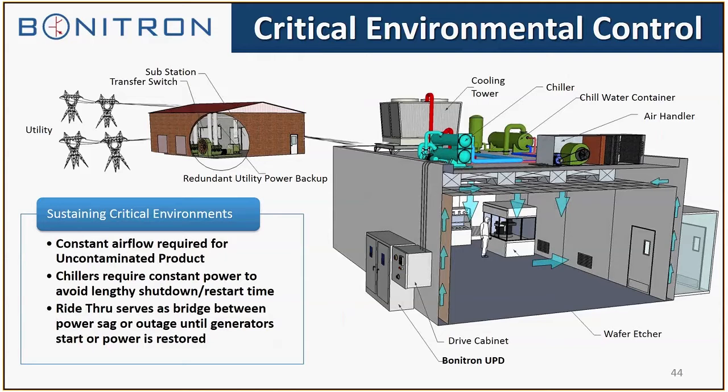And with a lot of these critical applications, you're going to have what I talked about earlier, which is redundancy. You're going to have a UPS, it's backing up the distribution point, but this does not cover process level problems too. So even though you got the utility covered into the plant with a UPS, there may be internal plant things that happen, load shifting, failures in other lines, other clean rooms that cause a problem with the power.